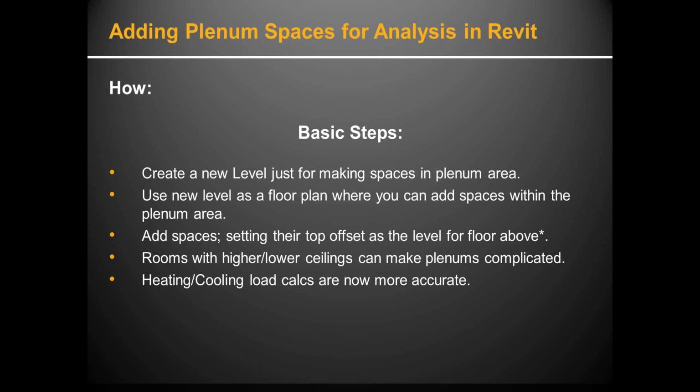And I made a note in here, setting their top offset as the level for the floor above, asterisk, because that's going to change just a little bit. It depends on what's above. Could be a roof, could be several different things, but I didn't want to go into all those caveats on a slide. So let's add these spaces.